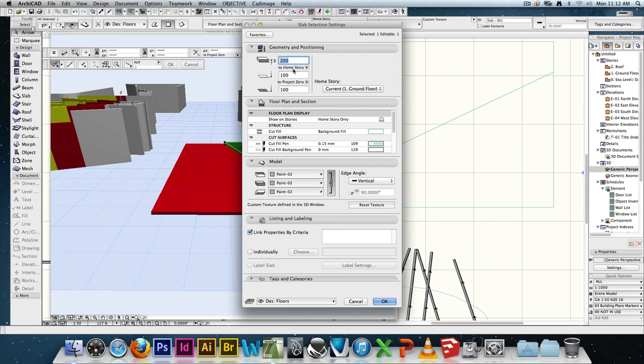So you select your slab, go to the X, and then just draw a line through it. So click. Remember, only single clicks. Click, click, not click and hold. Oh, okay, I'm dragging. Yeah. So you're not gaining or losing anything. Then which side do you want to keep selected? Right. Then you can change the top height, or you can change the colour, or do whatever you like. Delete it.